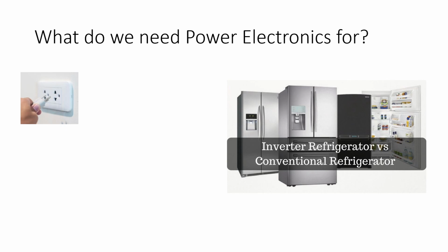Let me explain a little bit more of the technical terms for the inverter. Actually, the motor is a kind of AC motor. With an AC motor, when you want it to work hard, you need it to spin fast. If you want it to work not so hard, it spins slower. So an inverter is a kind of electronic device that can generate AC voltage and change the frequency to change the speed of the motor, changing the frequency and also the amplitude of the voltage. Okay, so actually this kind of technology just came out not too long ago.